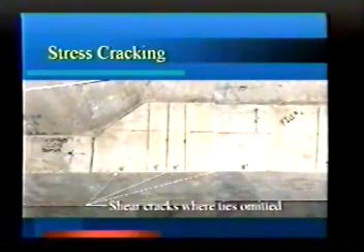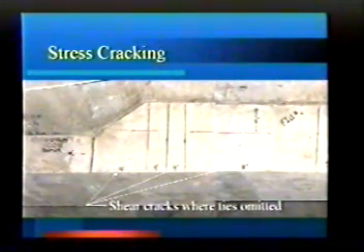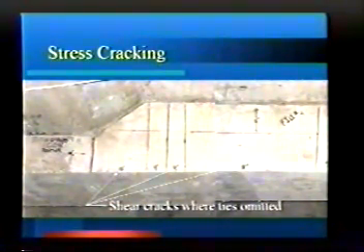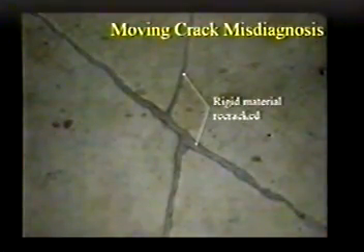Stress cracking. All right, back to that earlier girder that I had showed you. We had some other problems. That's getting a little hard to see on this slide. But right here, you can see there's a distance of 12 inches where they forgot the ties. It must have been because of the shape change. But right here, I have a diagonal crack. And what's that diagonal crack? That's a shear crack. Okay, we had the same thing going across here. Here's a large space without the ties. Again, it's a little hard to see in the slide from where you are, but there's diagonal cracks. So with the GPR, with the layout of all of the ties, we were successful in determining the source of what this problem is.